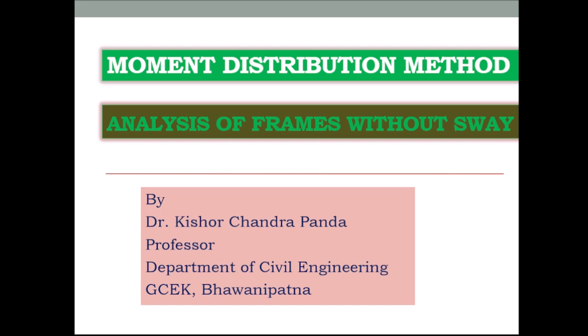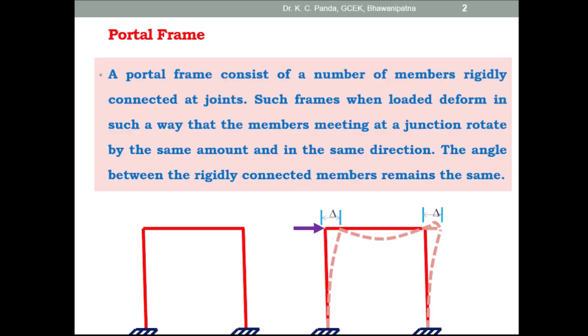In this lecture, I am going to present what is a portal frame and what is a non-sway portal frame, and what are the step-by-step procedures followed for the analysis of a non-sway portal frame by the moment distribution method. Then I would like to solve a problem on a non-sway portal frame by the moment distribution method. First, coming to what is a portal frame.